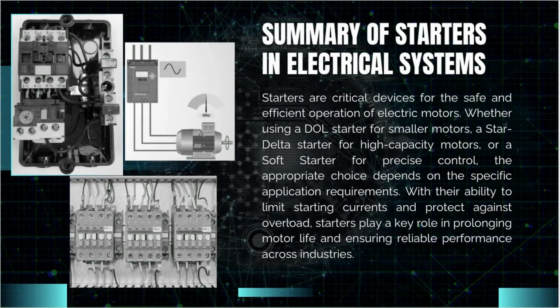To summarize, starters are critical devices for the safe and efficient operation of electric motors. Whether using a DOL starter for smaller motors or star delta starter for high capacity motors or a soft starter for precise control, the appropriate choice depends on the specific application requirements. With their ability to limit starting currents and protect against overload, starters play a key role in prolonging motor life and ensuring reliable performance across industries.